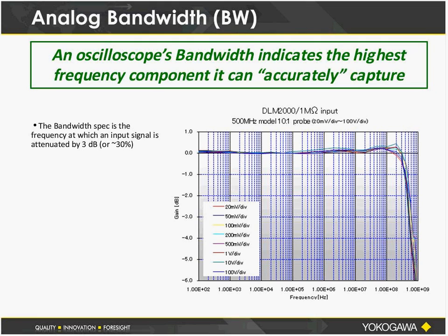So it's important to note that the bandwidth tells you it's going to be good for frequency content measurements, but you actually start having a little bit of roll-off well before the spec of the instrument if you want to maintain good accuracy. And again, keep in mind that accuracy specs on oscilloscopes are DC accuracy specs, and like a home audio system or speaker system, its amplitude accuracy is going to vary over its frequency range.